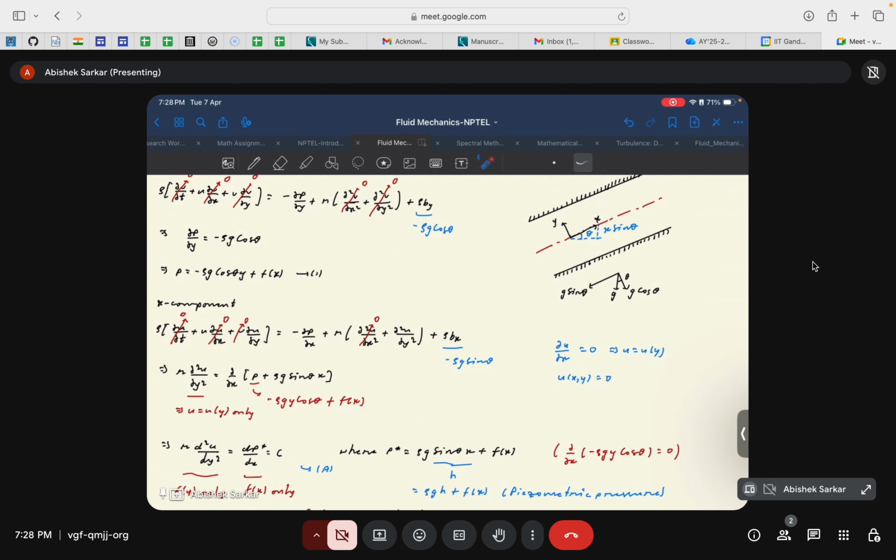We cannot obtain the exact solution if the non-linear terms exist, so we need to take the assumptions accordingly, of course, which make physical sense, that help us to remove these non-linearities from the equations. So considering the fully developed flow actually helped us in two ways. First was to remove this non-linearity, and second to make this flow essentially a 1D flow by making v equal to 0 for all the points in the flow field.